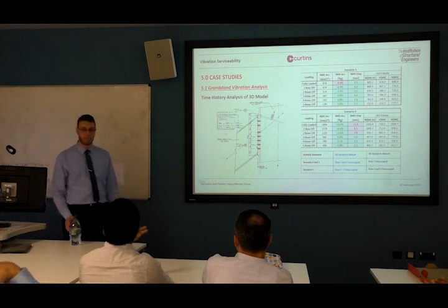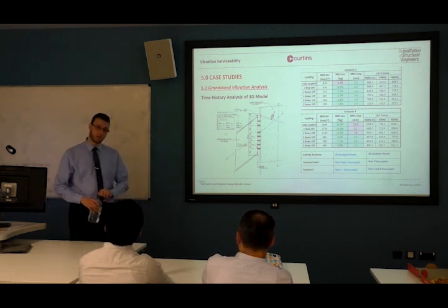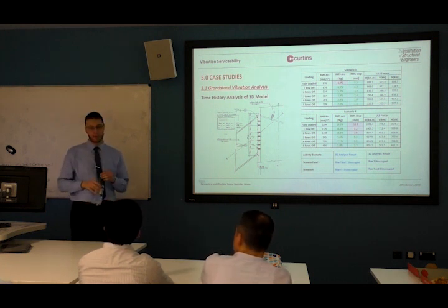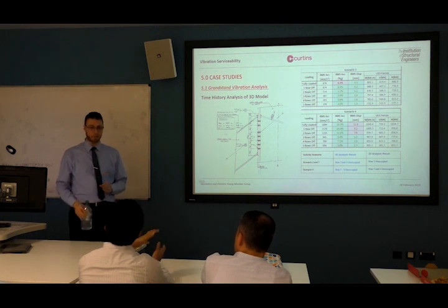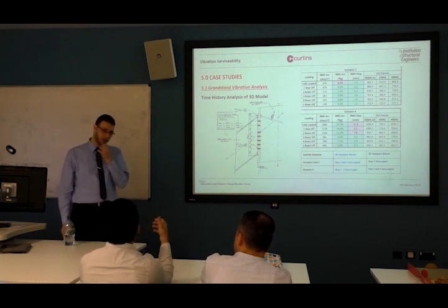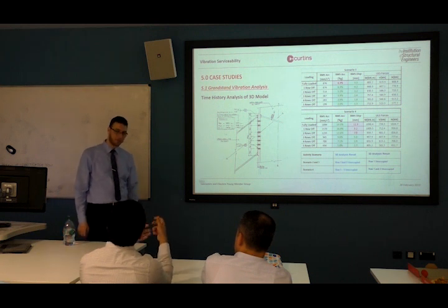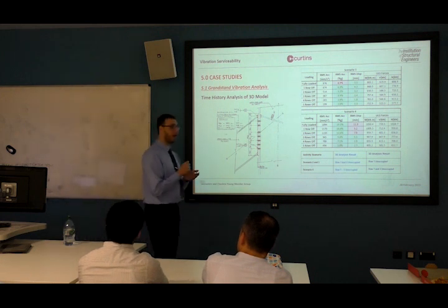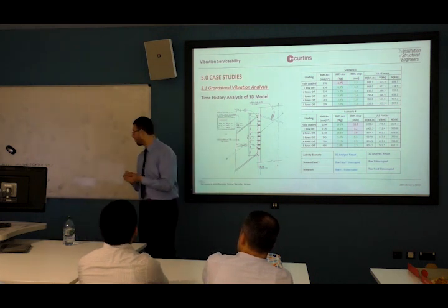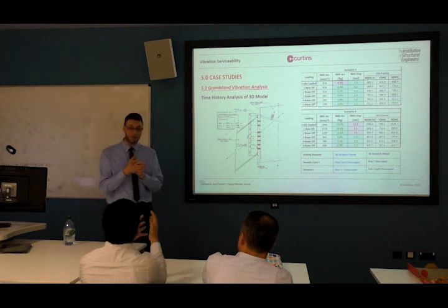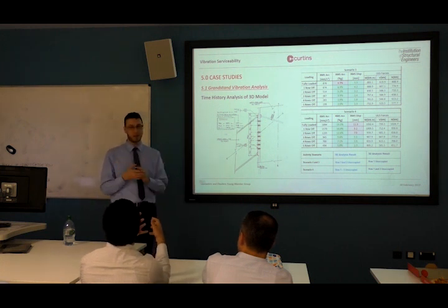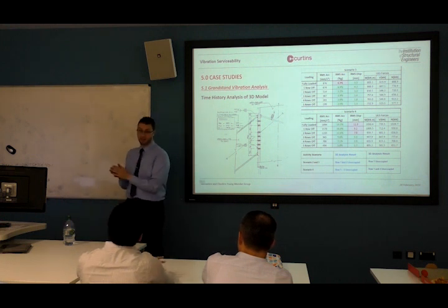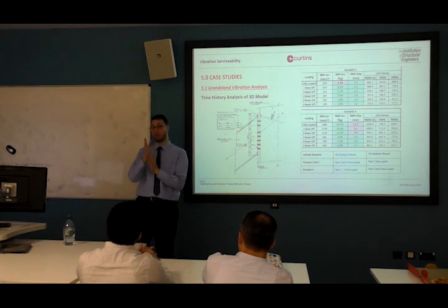Because it's suggested that, for example, IStructE in one of their technical notes, they recommend that you change that, even if it's a pin on site, you change it because of some friction. Okay. So if you have a pin connection, even a pin connection is not pinned in reality. We don't have something pinned, and we don't have something rigid. We have something in between.